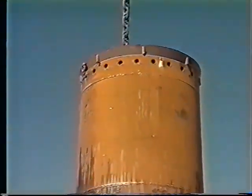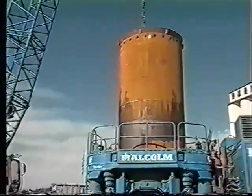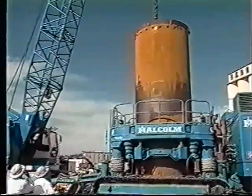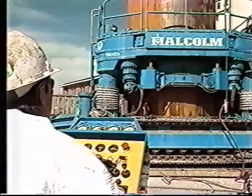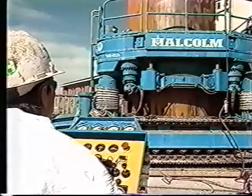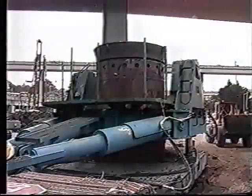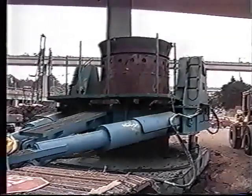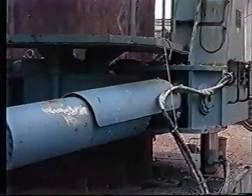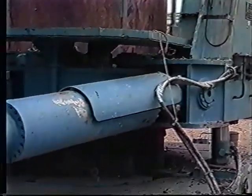Today in Europe, drilled shafts are predominantly constructed in a full-depth, cased way using oscillators and rotators. In North America, slurry-supported boreholes are more common due to the physical limitation of the equipment presently being manufactured in the United States. The oscillator rotator casing method utilizes a circular collar to clamp onto the drill casing. The collar rotates 20 degrees in alternating directions.